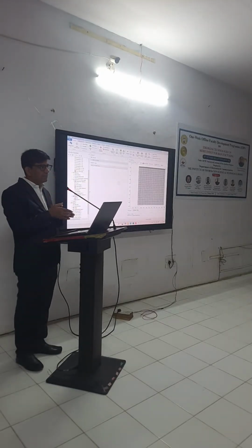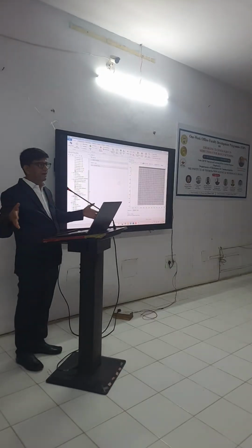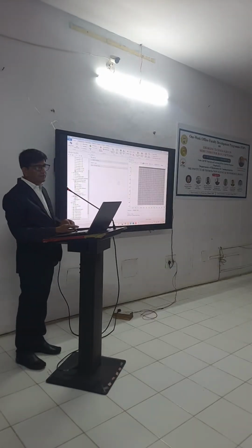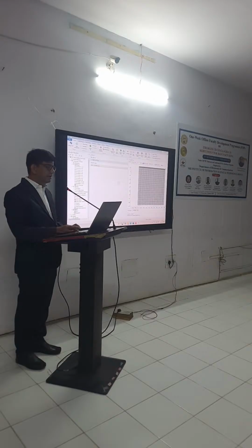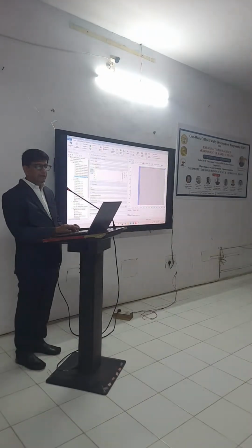Then we also need to define a PML layer, left and right side, so there is no reflection of your acoustic signal outside the device. So here you can see this portion is your PML layer. That is the perfectly matched layer, on the left hand side and right hand side, both sides. So we define this PML layer. Where will we define it? We define this PML layer in here. See, this is my PML layer.